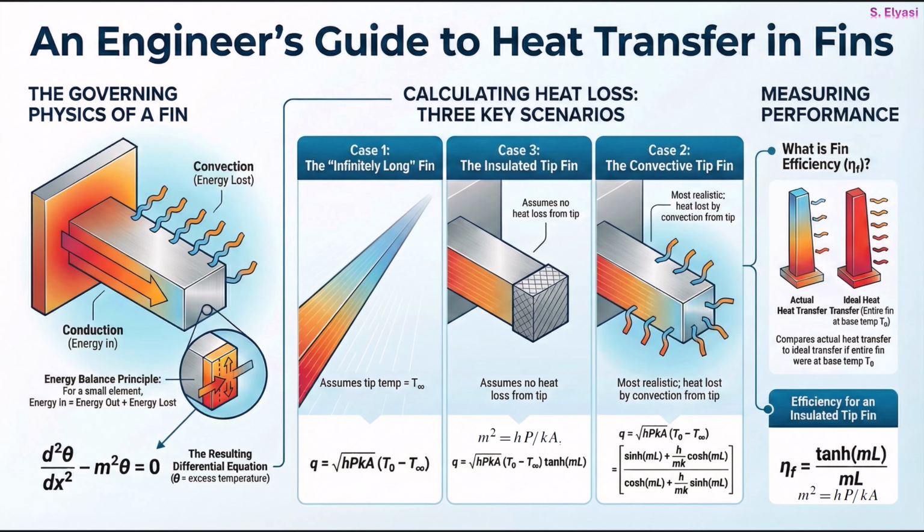It all boils down to this thing called the energy balance principle. Just picture this. Heat is trying to travel along the fin, that's conduction, but at the very same time, it's escaping from the surface into the air around it. That's convection. This constant balancing act, energy in versus energy out, is what we need to solve for.